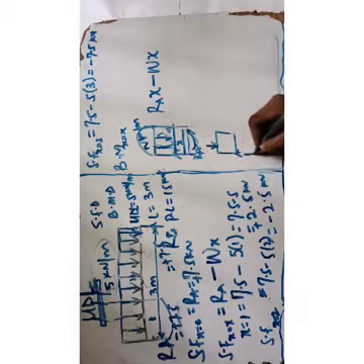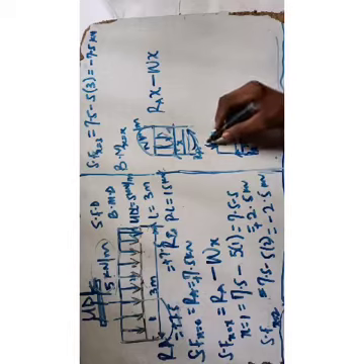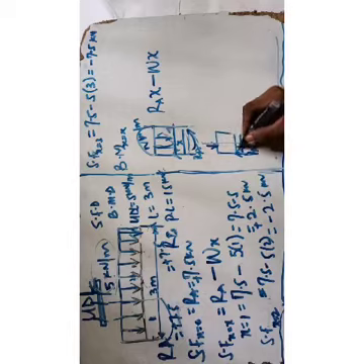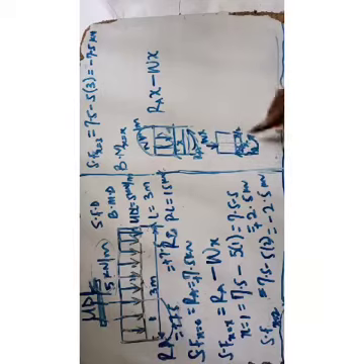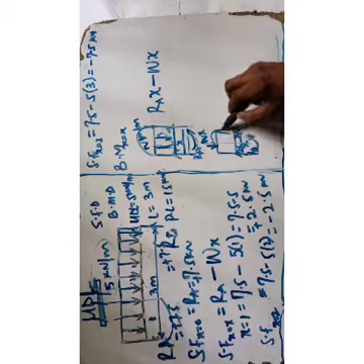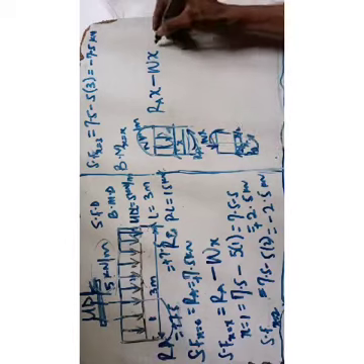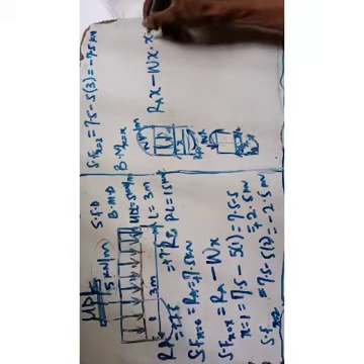My R will still remain, my x remain, but when it remains at center, here will now be x over 2 and x over 2. So that will now be RA times x, then my W, I've converted to point, that will now be WX. So that will be RA times x minus WX times the remaining half length, minus WX times x over 2.